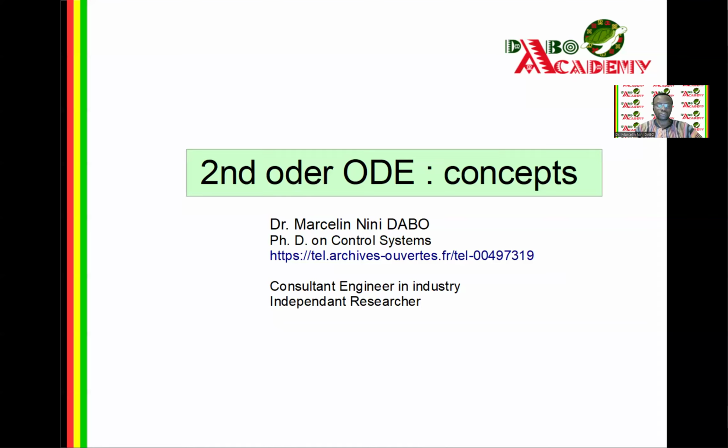So you can compute the time constant of your system only when you fix yourself in a 1 point for a first order system, not necessarily at 63% for an initial response, for example. You can choose 20% and you will be able to compute your time response. And then also, in a third video, I have introduced a new criteria, a new paradigm to identify a first order dynamical system.